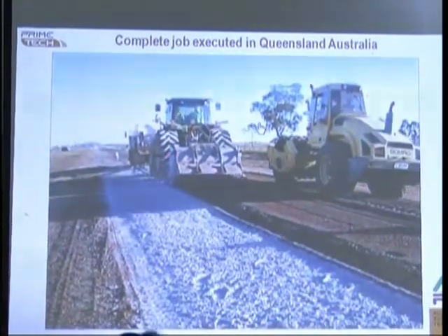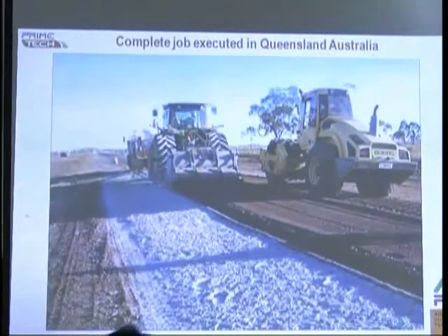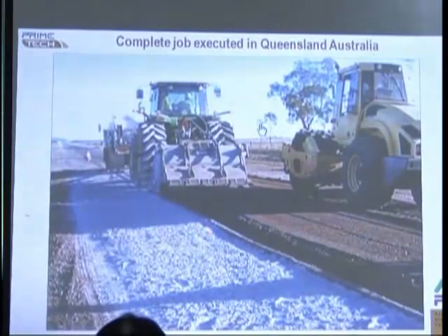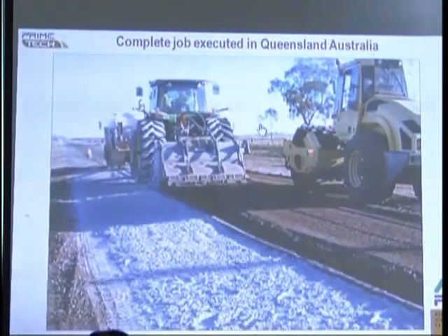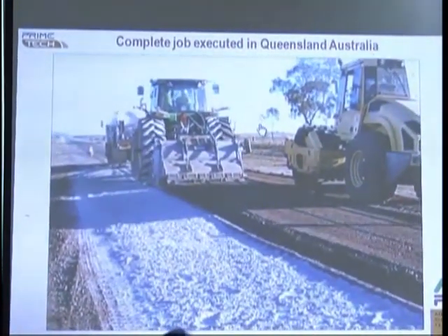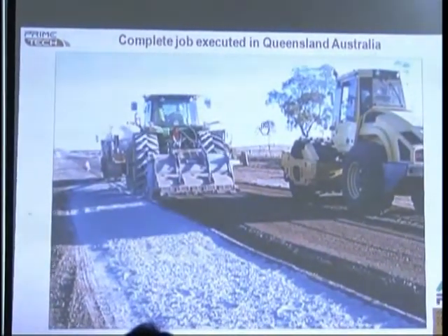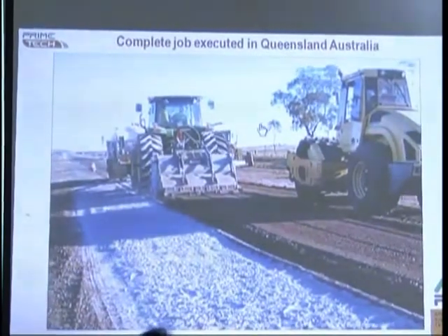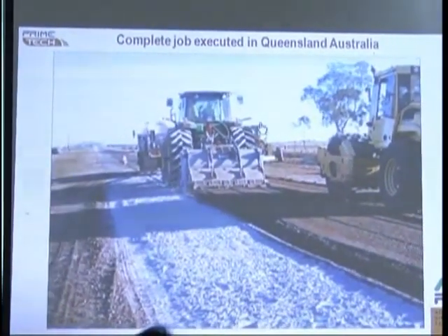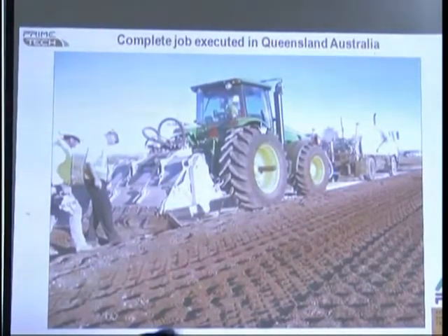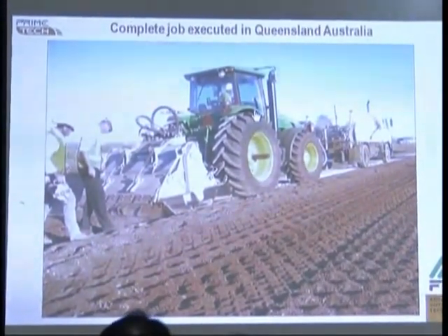Now they're mixing. So you can do many activities at the same time. For example, now they are mixing with water and cement. At the same time, the vibrating roller is doing this part. And actually, if you have a wide road, maybe an 8-meter road, you can close only half of the road and you can have traffic on the other half, because you cannot block all the road. You block half, and then traffic is still going on the other half.